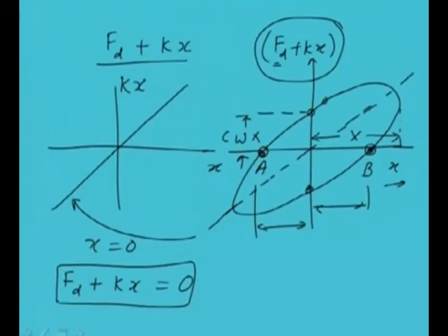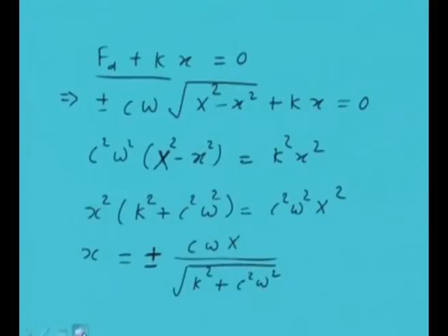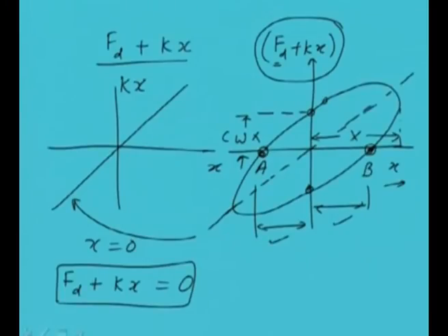One is positive and another is negative. Both have the same magnitude. At the same location they are becoming 0. So if you see this particular curve, it is confirming this well-known Voigt model, in which a dashpot is connected with a spring in parallel. So it is confirming this particular model.